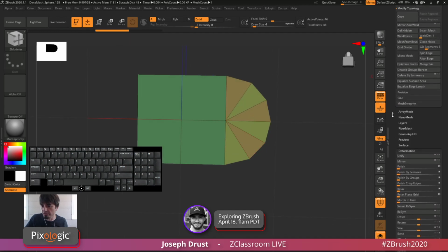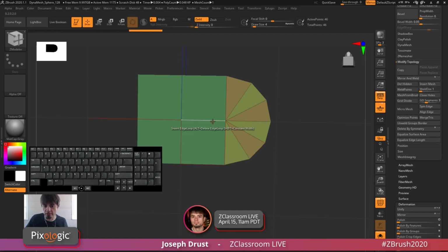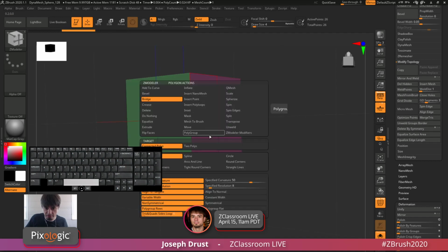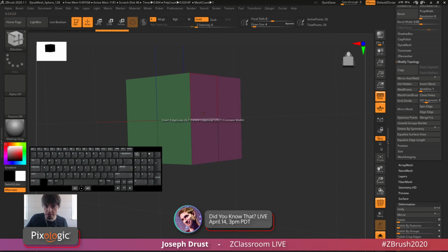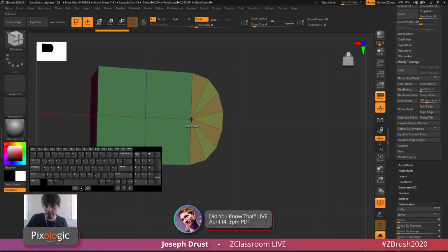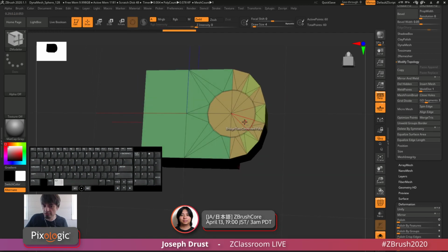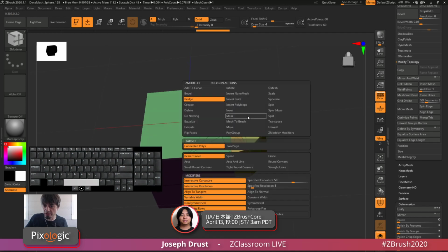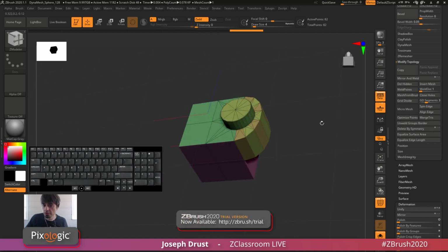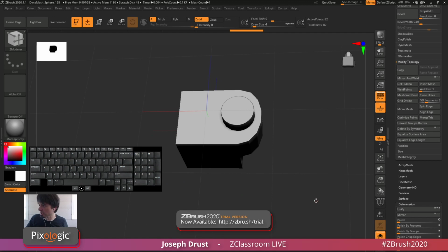If you ever need to weld stuff too, you can go to the modify topology area and click weld. And there's an option for triangle on this bridge connected poly too, triangle sides versus quad sides. That will determine how that middle point gets generated. And now this should split a little better. And so then I split this, and then there's an option for ringing it as well. So that will now make it circular. And then you can come in and punch this out or make it grow. And there you've got that kind of shape. So that's what was done with those other pieces.